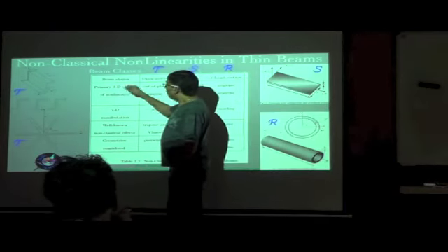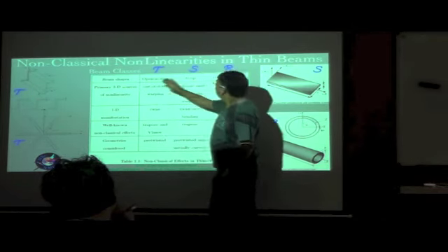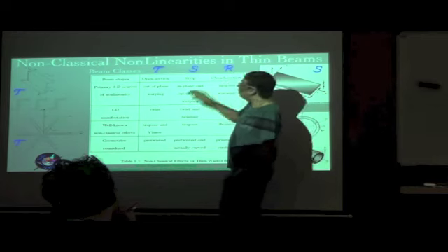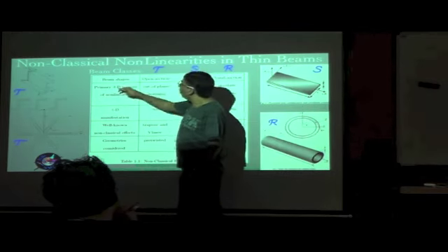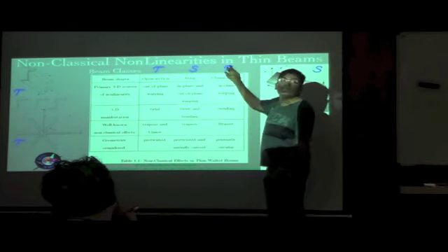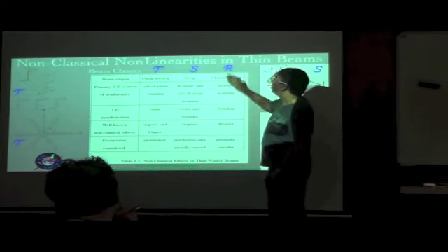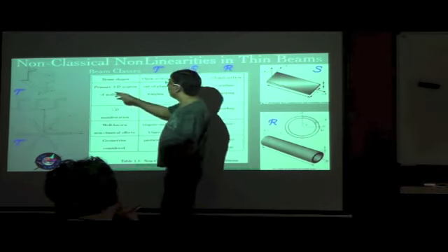Now the beam shapes that we have corresponding to those are open section, strip, and closed section. And then you have certain nonlinearities arising in each one of those. In this case, only if it is thin-walled. If it is thick-walled and/or solid, it will not be there. The situation where it is thin-walled is what I am discussing right now.